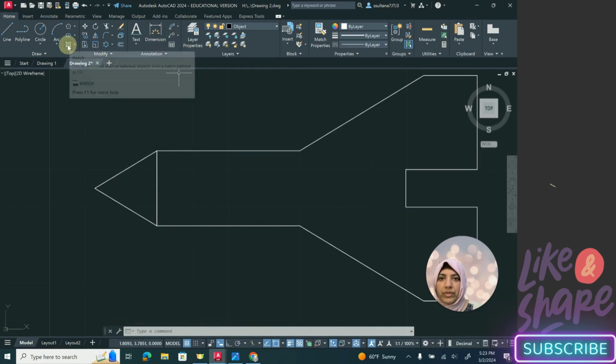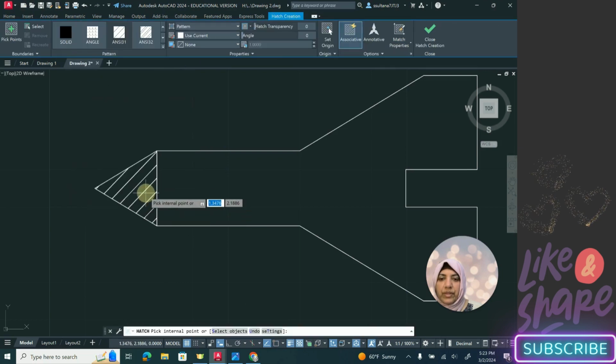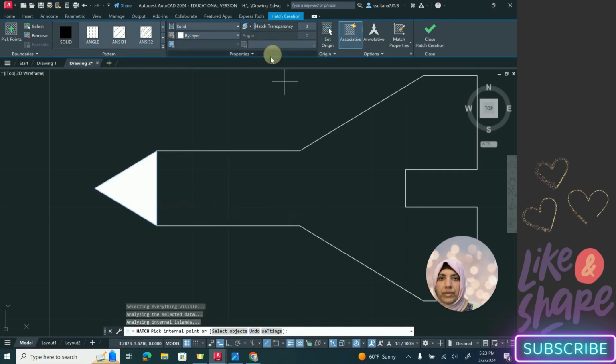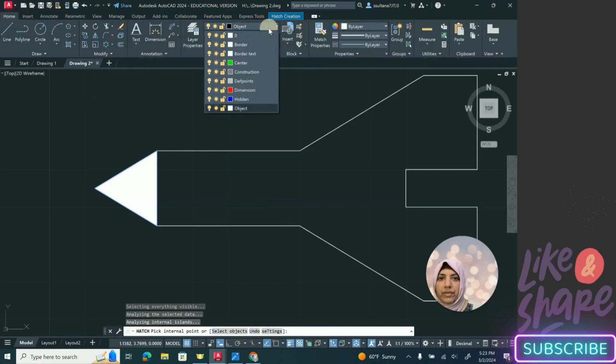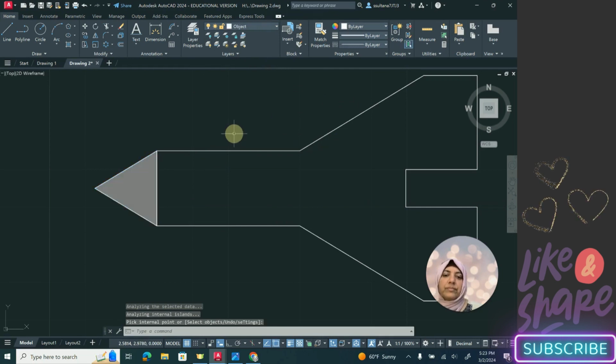Now you're going to use hatch and click inside the rectangle. I'm going to use solid hatch. And I'm going to give it a gray color, put that in construction layer.